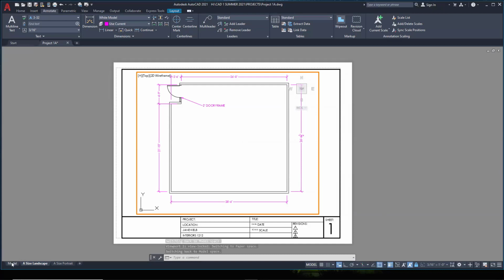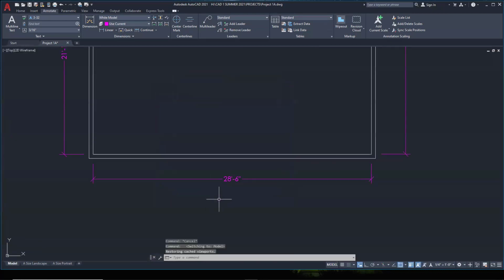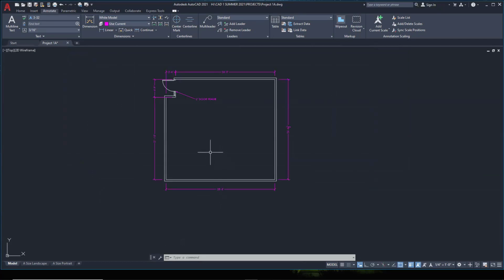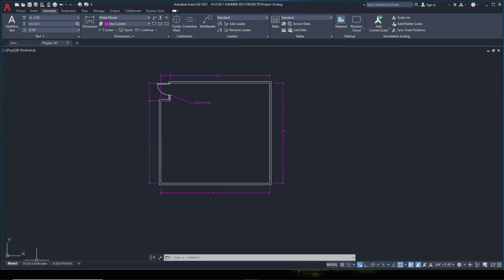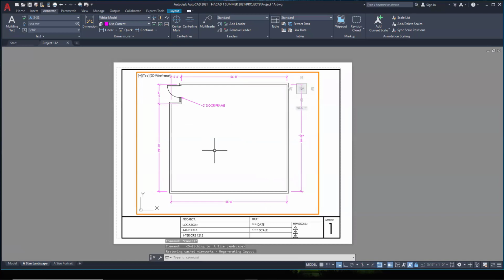If I drew it in here, this text would be like, well, this wall is 5 inches, so this text height would be like 8 inches. And it's just too confusing. You don't want to do that. So when I'm doing my dimensioning and my text in paper space through a paper space viewport, AutoCAD sets that dimension for me. So yes, you are correct that by doing it this way, these sizes are set for us.